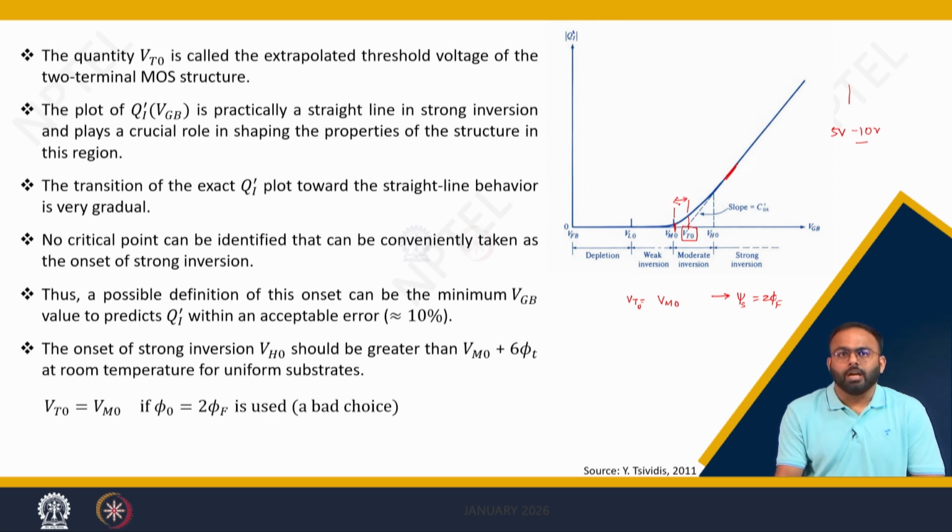However, in the recent era, when you are talking about low power devices, when your supply voltage is a maximum of 1 volt, 0.8 volts and so on, in comparison to 800 millivolts, the change in this millivolt is significant, and hence you need to choose this VT0 precisely.